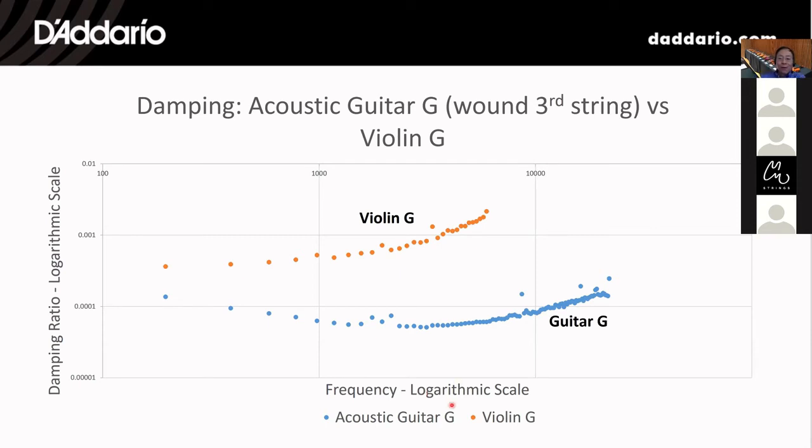The one exception is the plain steel violin E string. Even though it's got incredibly low damping, it seems to work fairly well. I think that's because the frequency is high enough that the absolute time it takes to start the string is reasonable, and it has very low bending stiffness as well.